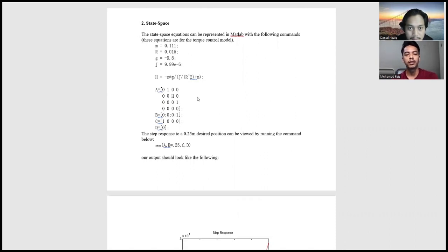And for my part, I will show the result in the state space, which is the linearized system equation, which can also be represented in state space form. This can be done by selecting the ball's position and velocity as the state variables and the lever angle as the input. And the state space representation is shown in the form of matrices. However, for our state space example, we will be using a slightly different model. The same equation for the ball still applies, but instead of controlling the position through the lever angle theta, we will control the alpha double dot.